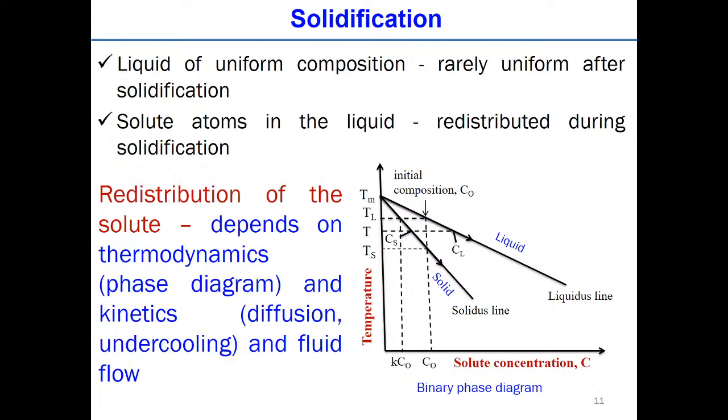When solidification happens, the solid liquid interface moves gradually towards the liquid as it solidifies. Just in front of the solid liquid interface, a composition gradient may exist, and it normally happens in the case of the binary alloy system. The variation of the composition induces some sort of constitutional supercooling.